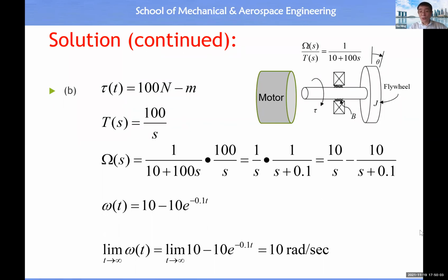All right, okay. So once you have this simple Laplace transform, you see 1 over S in time domain is 1. But this S will undergo a shift. Once you undergo the shift, then in time domain it is equal to 1 times the natural exponential function raised to the power of negative 0.1 t, because this is a shift equal to negative 0.1. Done already. Okay, then you can estimate what the steady state response of this omega should be.